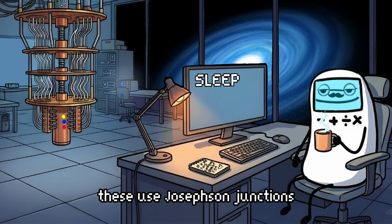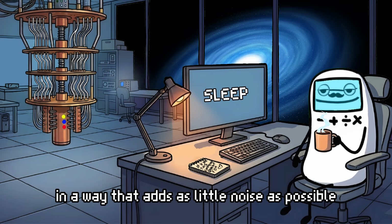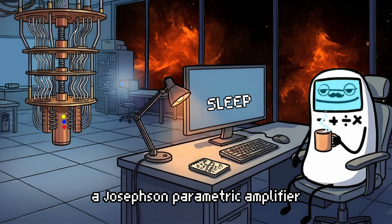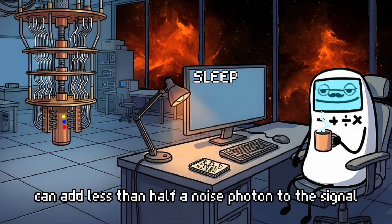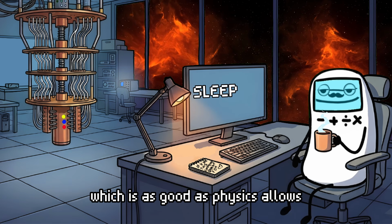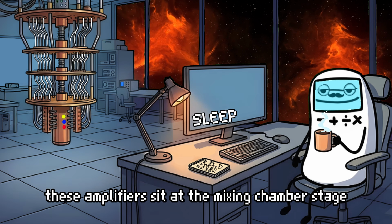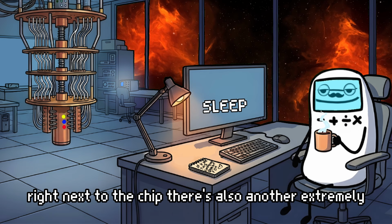These use Josephson junctions to do amplification in a way that adds as little noise as possible. A Josephson parametric amplifier can add less than half a noise photon to the signal, which is as good as physics allows. These amplifiers sit at the mixing chamber stage, right next to the chip.